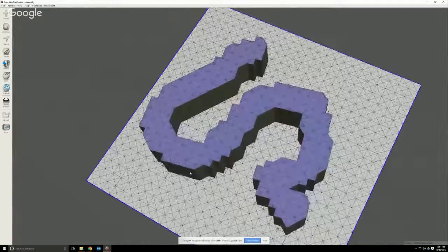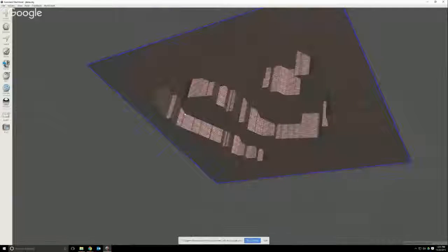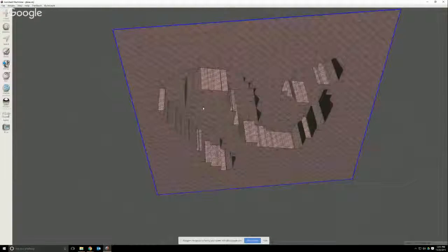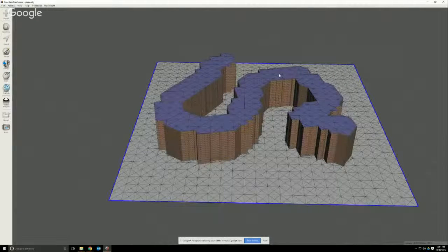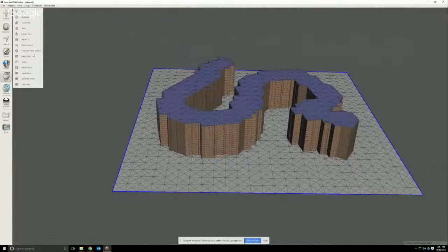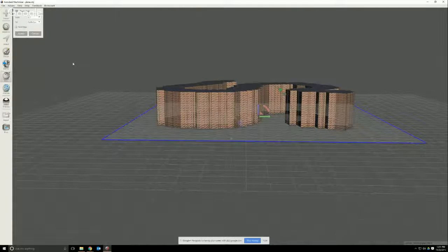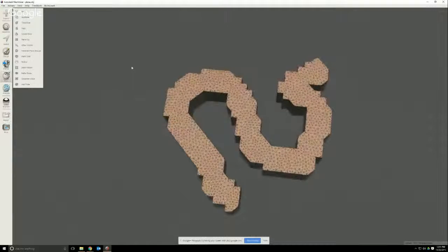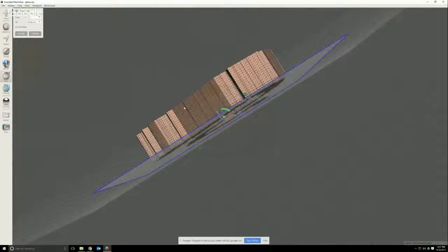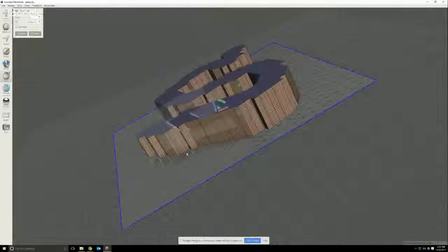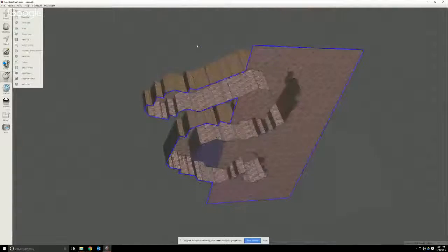But anyway, you've gotten a really nice base image right here to start doing things with. The problem is that you started with a plane and you have back faces underneath. So if you go to 3D print this, it just won't work. But the very easy way to do this, if this is the shape that you want, this kind of S snake shape, is to go into Edit, to Plane Cut, and cut off just the very bottom. I'm just going to click Accept, and now you're able to work around with this shape.